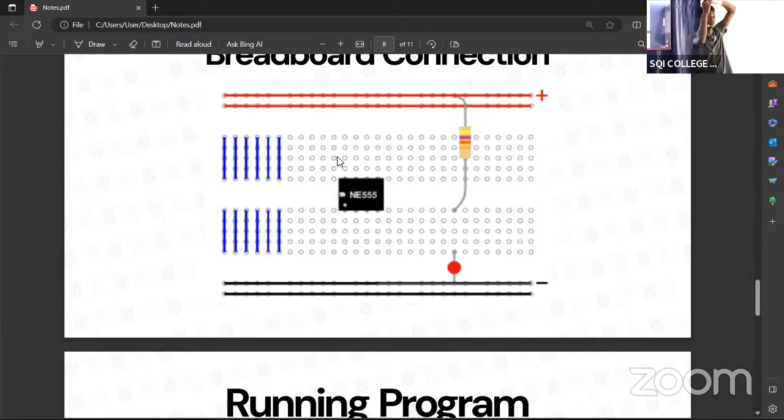All the pins on this row down are connected together. And then all the pins on this column, down this way, are connected together, except it has a demarcation here. Just from here to here, and then from here to here is also connected together. This and this is not connected. This place and this place is not connected. So there is a demarcation in between. So you have 1, 2, 3, 4, 5 connected together, and then 1, 2, 3, 4, 5 connected together. So we have to learn our proper breadboard usage.